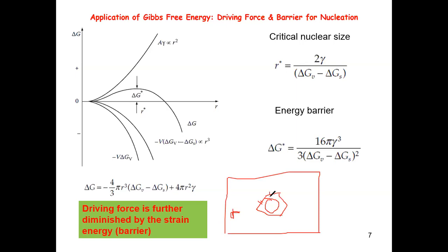And if you do have something like that, a polyhedral nucleus, one important distinction is that each surface is going to have a different surface energy, because each of these beta-alpha interfaces is going to have a different orientation with respect to the original alpha phase field. For different orientations, you have different grain boundaries and different energy. So you cannot simply write something down like that.